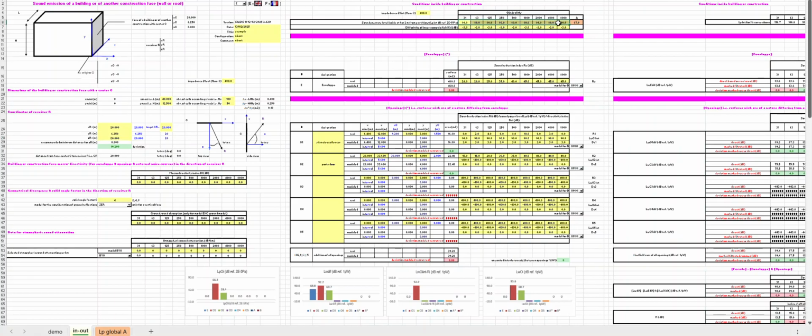Now we can enter a sound pressure level inside the building at 1 or 2 meters from the partitions per octave band, and we can select a diffusivity term which is variable depending whether it comes to a reverberant acoustic field or a free acoustic field, with all possible variations between those two states. For the envelope, the area is calculated by a subtraction of the openings area, and we can enter the sound reduction index.